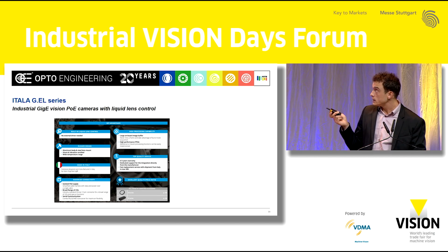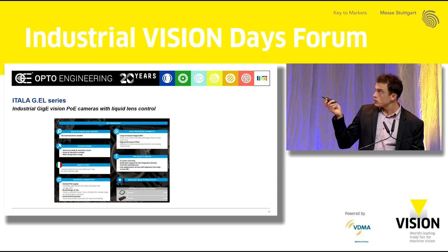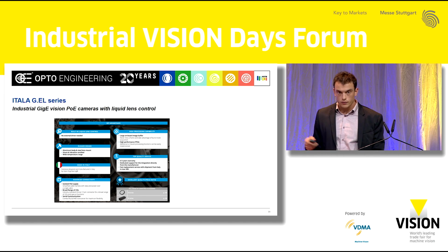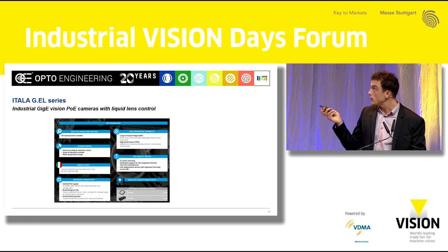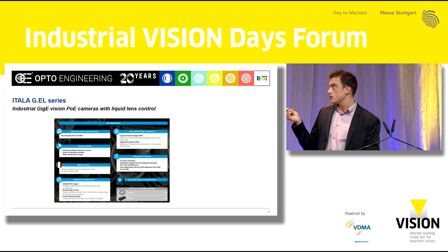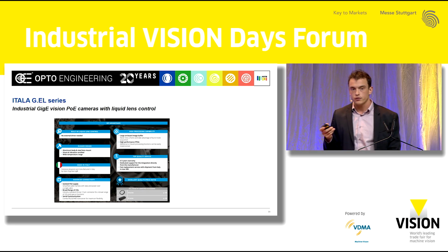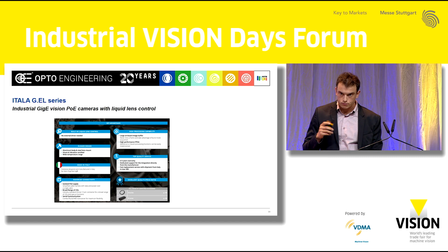The cameras are made in Italy, and they grant high connectivity thanks to isolated PoE supply, a broad range of IOs thanks to an M12 12-pin connector, so a lot of inputs and outputs are available. And they also feature serial communication, so a combo RS-232 or 485 interface for maximum flexibility.